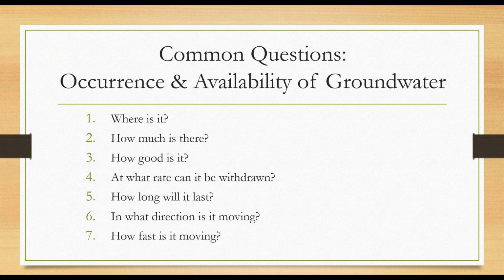Another common reason for collecting groundwater data is to understand at what rate water can be withdrawn. How much can I use? Determining a safe yield of a well can be complex and require quite a bit of groundwater data. Another question is, how long will my resource last? How long can I use this resource? Similar to the previous question, to answer this you need to know long-term trends or long-term recharge or hydraulic properties of the aquifer so that you can assess how long your resource will last.